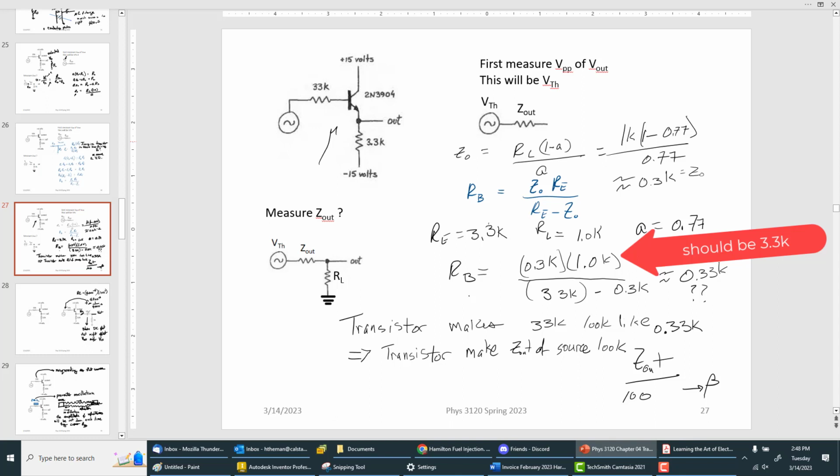And the load matters because we need to know what is the Thevenin resistance or the Z out of a source. And the emitter follower is basically an impedance changer. So it's amplifying, but it's doing it in a hidden way. It's a very powerful little thing.